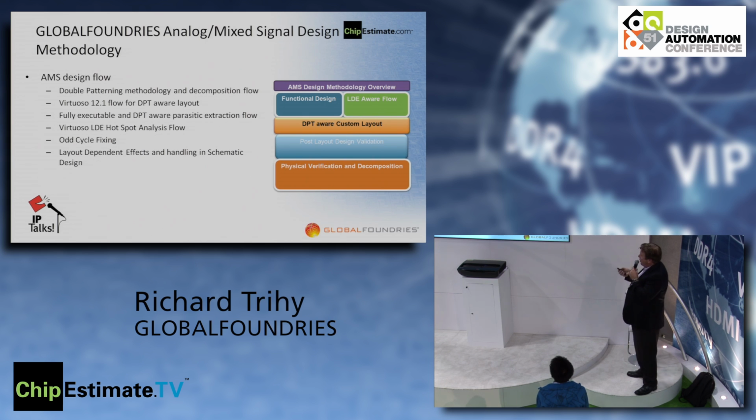And so here in this case, for analog mixed signal, we implemented a real chip. And then in the process of implementing that chip, we captured all the learning into different modules. So you, the user, can run each of these modules standalone to learn about some specific topic. So in functional design, we talk about which corners to use, Monte Carlo simulation, how to use the LDE models to estimate layout-dependent effects. There's also a double patterning aware custom layout flow, again, where we highlight the use of Virtuoso 12.1 in order to be able to efficiently perform double patterning aware layout.